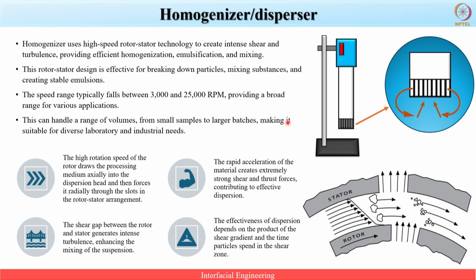If we talk about the continuous mixing case, this process liquid is expelled from the stator slot and re-enters the cycle. This repeated action ensures uniform mixing of the sample. This force also breaks down the large particles or droplets into smaller ones, leading to uniform dispersion or emulsification.